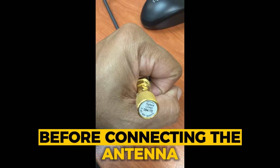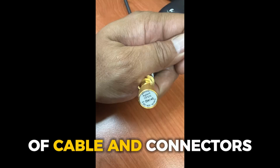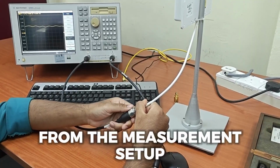Before connecting the antenna, the VNA must first be calibrated. Calibration removes the effect of the RF cable and connectors so that the measurement represents only the antenna itself. Without calibration, the measured S11 could include unwanted errors from the measurement setup.